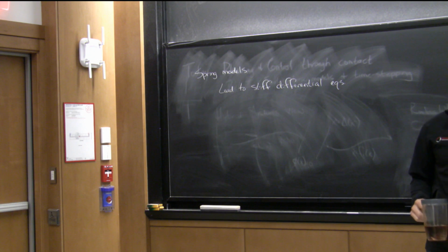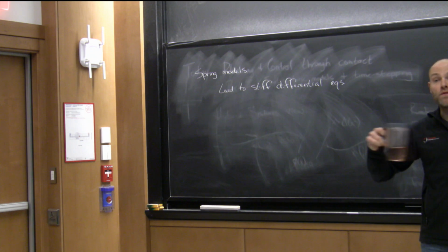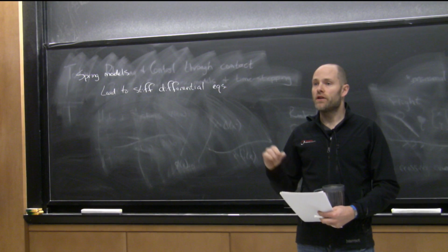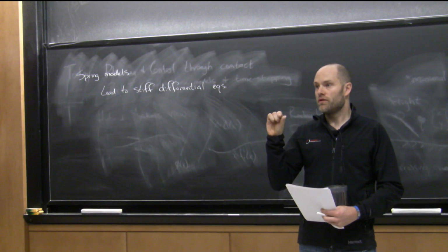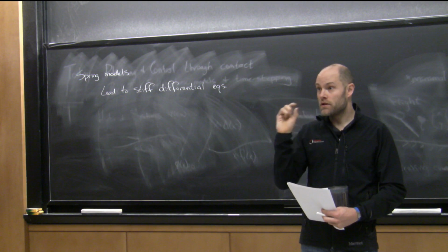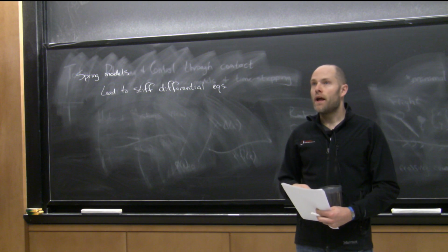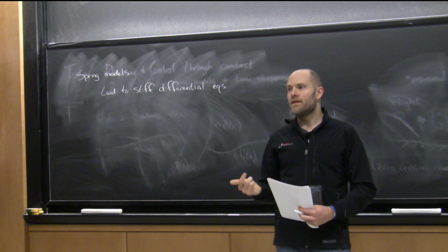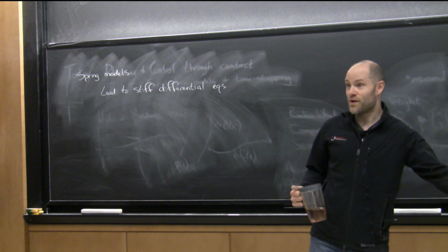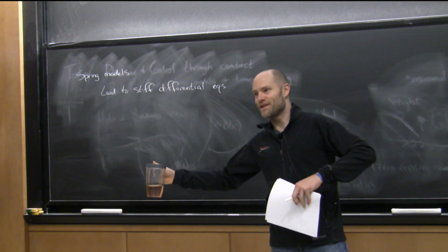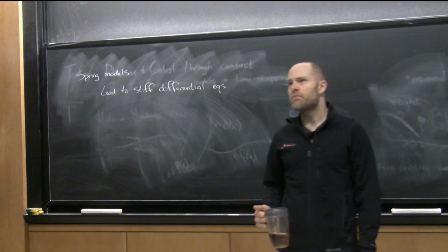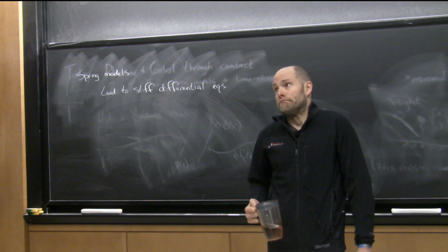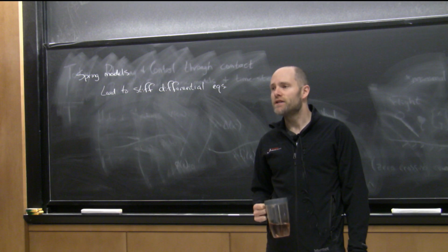So the question was, if you were to let your trajectory optimization move the knot points, does that help with it? I think it could help with that, but you would have to put something about accuracy into your cost to force them to move and try to be more accurate. And that is possible. It's a little gross in some sense, because now you might have a solution that is less good for the robot, but you're competing with an objective that's just trying to make your solver good. And in practice, people haven't done that as much. I think you could, but I think there's better ways.